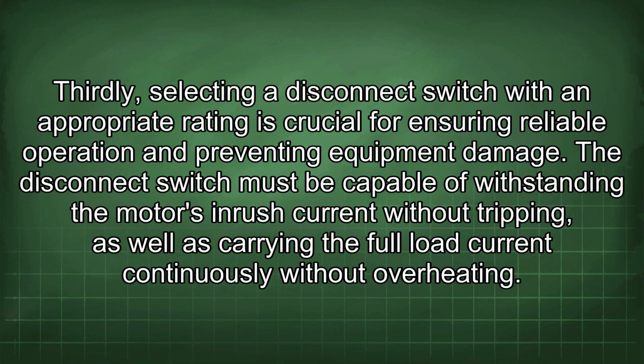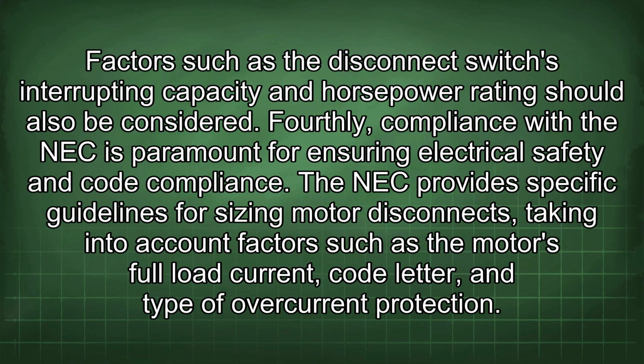Thirdly, selecting a disconnect switch with an appropriate rating is crucial for ensuring reliable operation and preventing equipment damage. The disconnect switch must be capable of withstanding the motor's inrush current without tripping, as well as carrying the full load current continuously without overheating. Factors such as the disconnect switch's interrupting capacity and horsepower rating should also be considered.